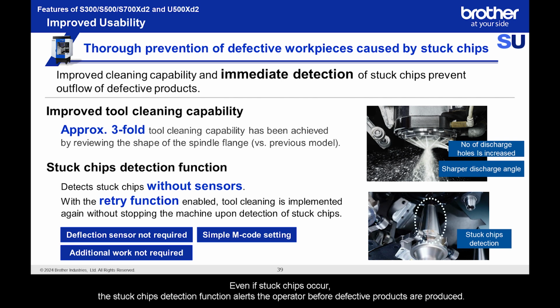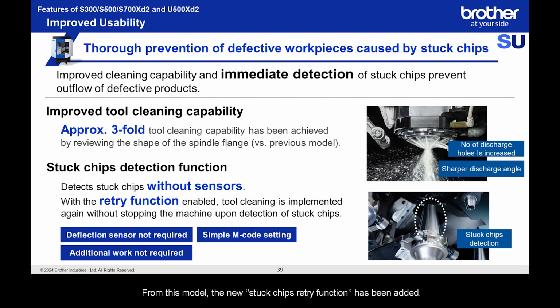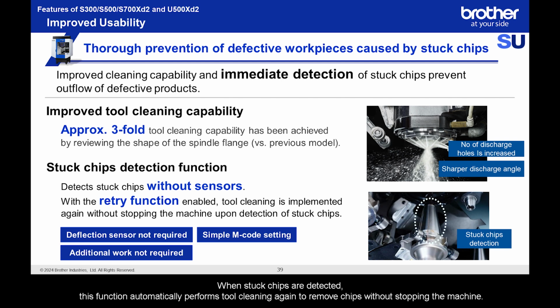Even if stuck chips occur, the stuck chips detection function alerts the operator before defective products are produced. From this model, the new stuck chips retry function has been added. When stuck chips are detected, this function automatically performs tool cleaning again to remove chips without stopping the machine.